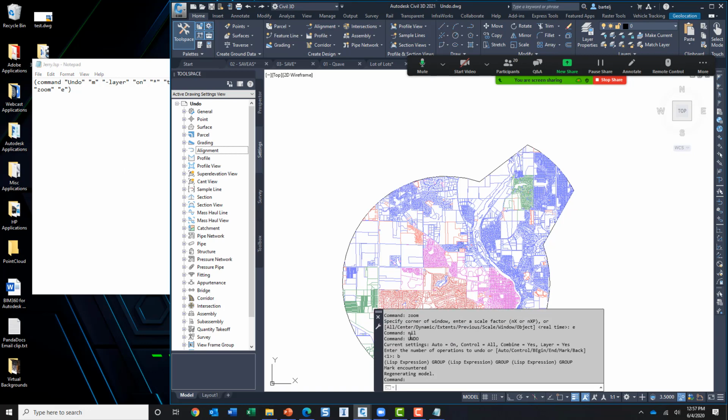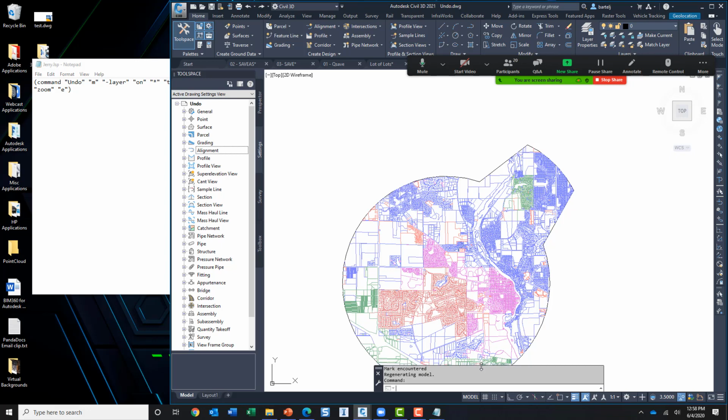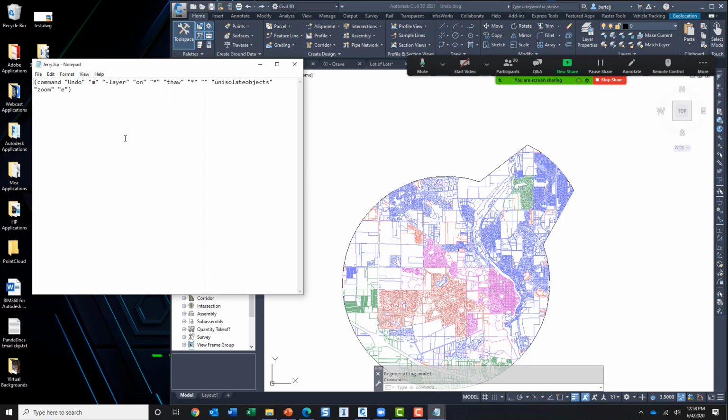When I run that, you see when the command is done, it says nil. It's not a big deal. It's just one more thing that, when it's over, the LISP that was created is not passing back any value, so it says nil. We can suppress that from the screen just to clean that up a little bit.